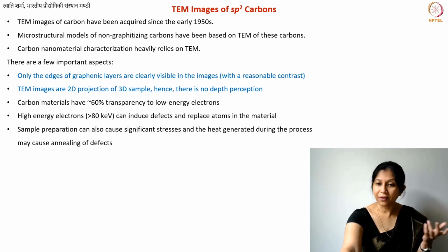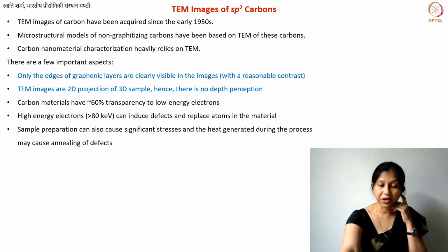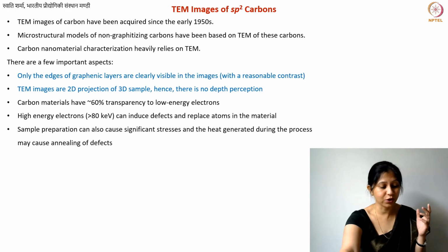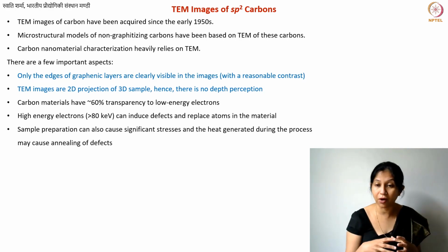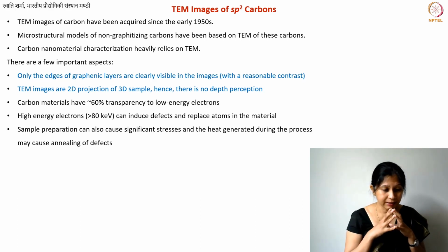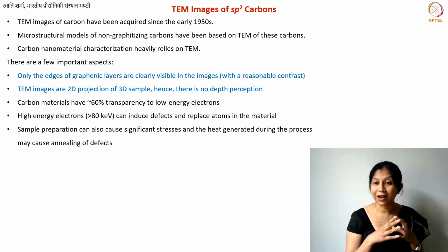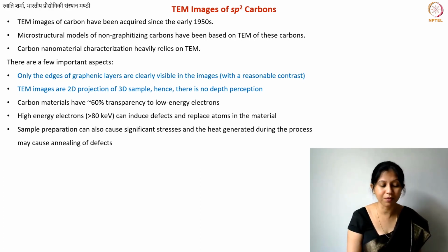Sample preparation itself, I already told you that this can already create defects. So you are often using either focused ion beam milling or some sort of technique for making powders. But in that case, you're definitely using very high energy to make these slices or to make the powders, and there you may also have higher temperatures occasionally, depending upon how you're making your sample.